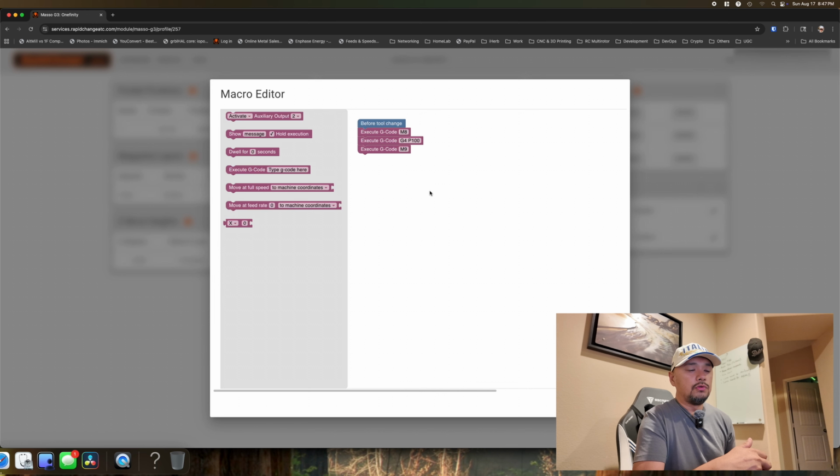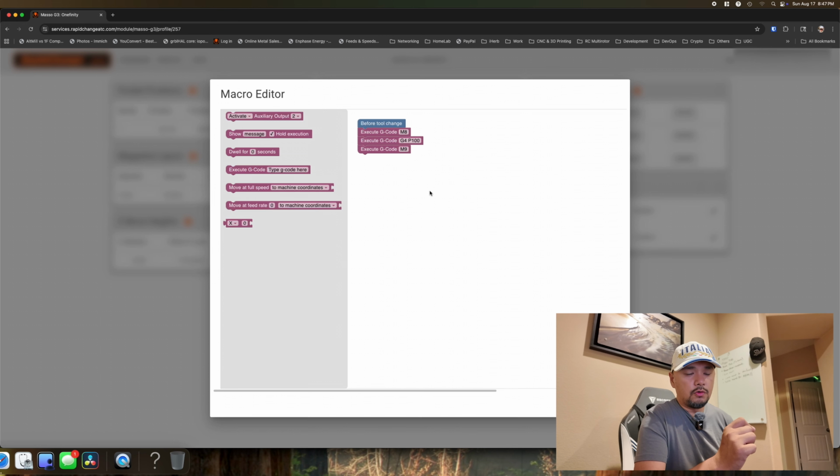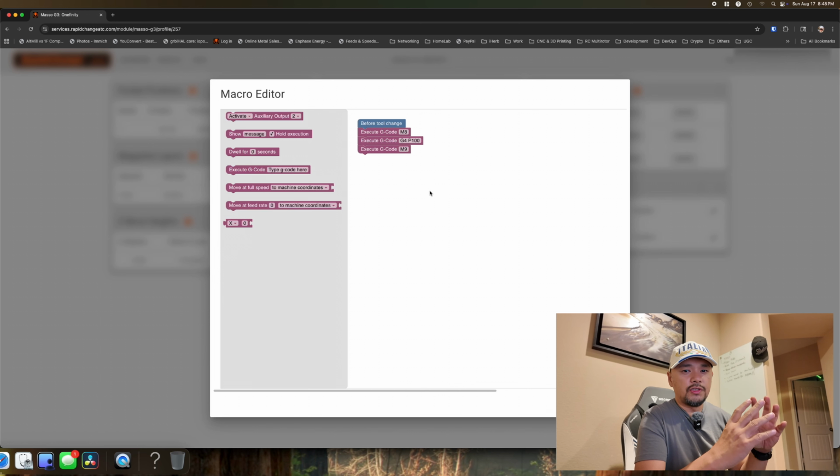So to safely force it to retract, we're gonna turn on the coolant flood, and quickly we're gonna turn it off. That guarantees that the state will change and that will trigger the AutoDustBoot to retract. It doesn't matter if the AutoDustBoot was retracted by coolant flood or by using the rotary knob on the AutoDustBoot. And the G4, why do we need a delay P100?